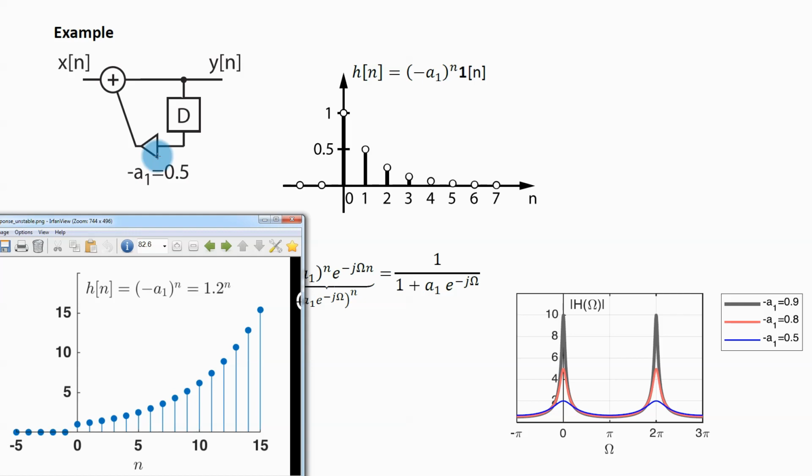In this specific case, it is rather unlikely that a coefficient like 0.9 would be rounded to 1.2. The rounding errors are typically much smaller. But with higher orders, nothing extreme, just for example something like 20, the IIR filters become very sensitive to even the smallest changes in their coefficients.